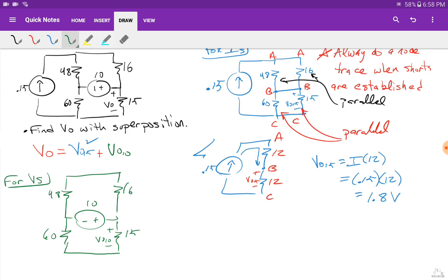All right, a lot of people will draw leads like that, but honestly, you don't need to do that unless you're looking for the voltage source. Unless you're looking for the voltage, the leads are actually negligible. They're just dangling pieces that may confuse you when it comes to evaluating the circuit properly, honestly. Okay, so this is what we end up having when we look at the contribution just from that 10 volt source. Now, I'm going to tell you this can be solved.